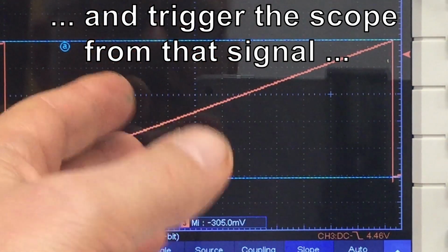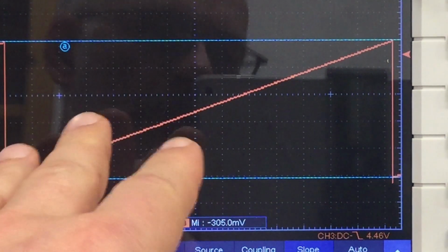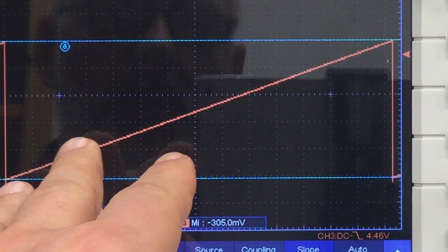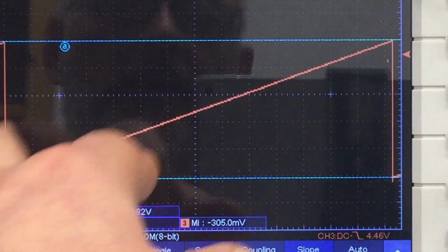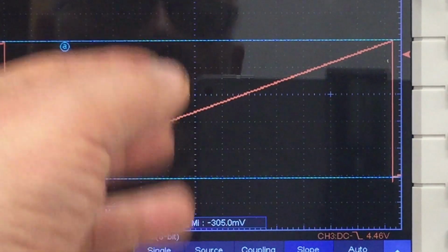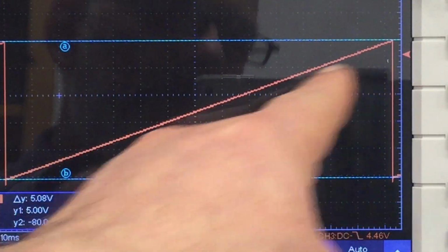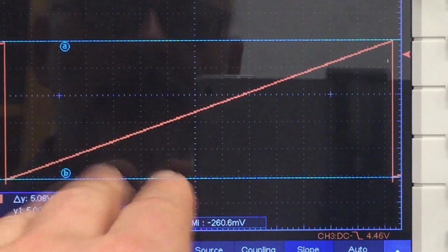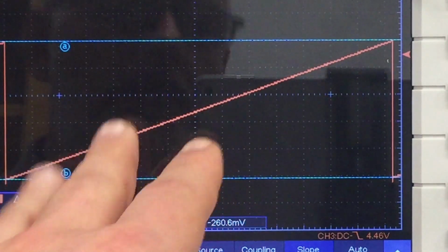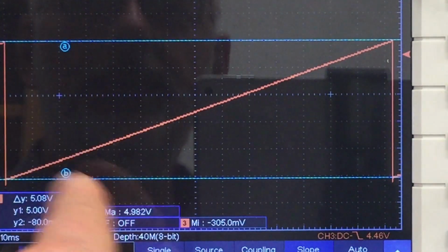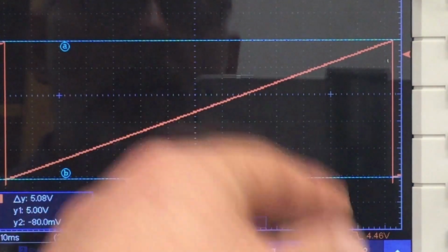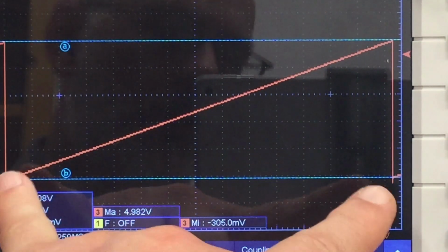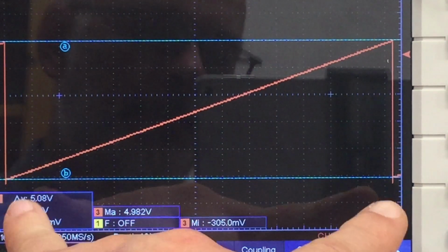The problem I ran into: if I put a 50 ohm termination at the input of the oscilloscope, I didn't get a linear curve anymore. At least not for the voltage range I need, and that is 0 to 5 volts. So I run this now without termination, which should be okay, because we are running that only at 7 Hertz. 7 Hertz was the combination where I got the most usage on the ramp out of my oscilloscope